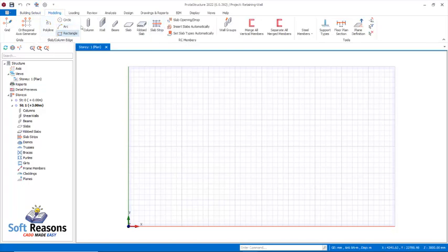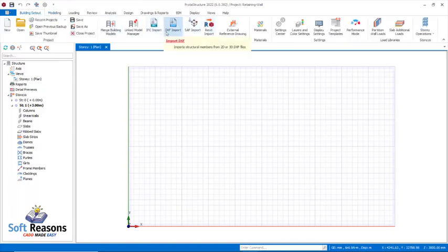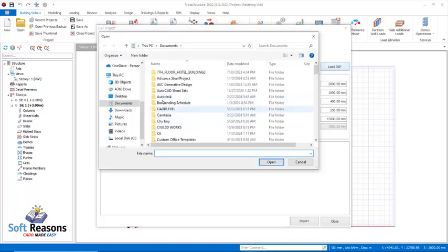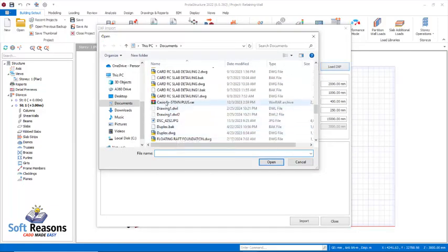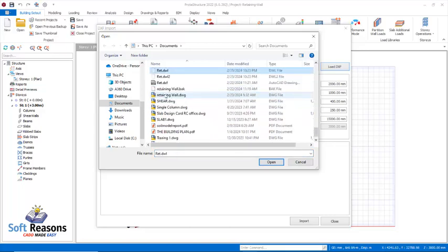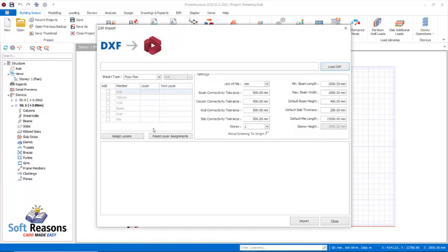Right there, we get to the import files through the building set out. We have a DXF import file, so we have to import the file we saved in AutoCAD. Through these provisions, you get to load the DXF file. You have to scroll down to that file. The file name is RET, so we check that out, which is this particular file. Get that selected, click on open.